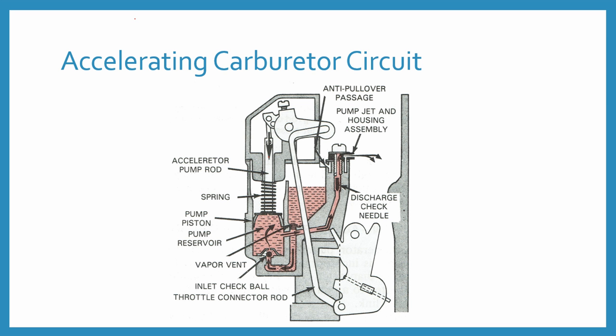But since the fuel has a higher specific gravity, a brief interval is required before the fuel gains speed and maintains the desired balance of fuel and air.